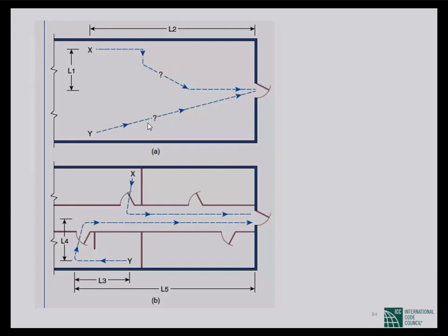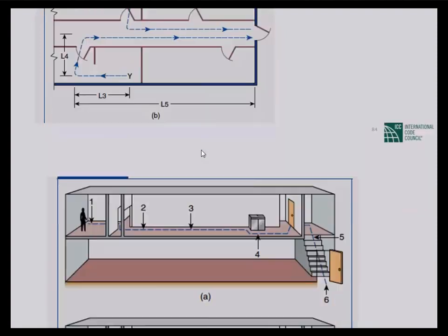Because distance means a perpendicular distance, but actually we mean the actual length the human has to traverse during evacuation. So whatever is said as travel distance in the NFPA, in BNBC by travel distance we mean travel path. In BNBC we use two words, travel path and travel distance. So travel path is measured in that way. You can see from here, if you see this figure, it is travel distance, travel path.